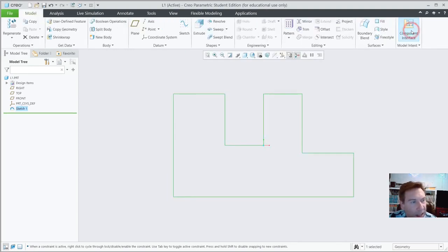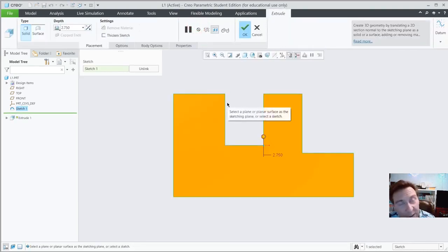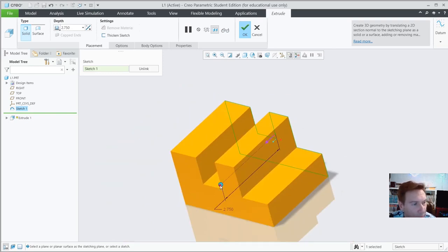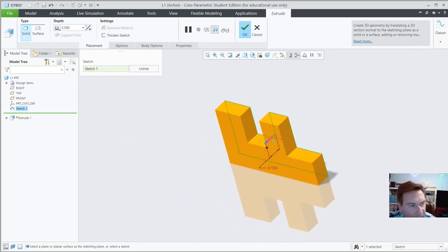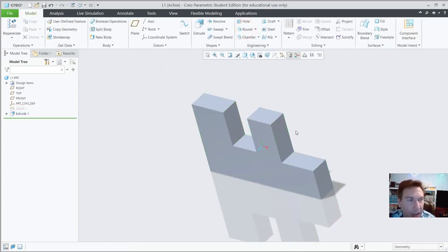We could go ahead and hit OK and go to extrude. Now the reason why we have to click extrude now is because I went with sketch. Remember I told you that trick? You could start with an extrude first or a sketch. Now I'm going to rotate this a little bit, and I'm going to use this little ball. This needs to be a 1/2 inch thick, so it seems to lock in 1/2 inches really well. Or you could type in the value here or here. Hit the green check. Okay, now I invite you to have fun with this. Experiment. This is your chance to enjoy this software.